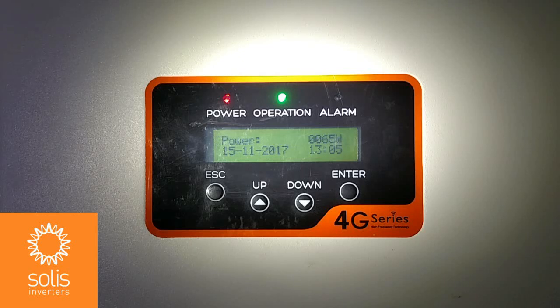When you choose this standard, you will be given options to change the upper and lower limits of the grid voltage and frequency allowed by the inverter. Warning here, technicians must check with their grid connection provider for the allowable upper and lower voltage and frequency limits.